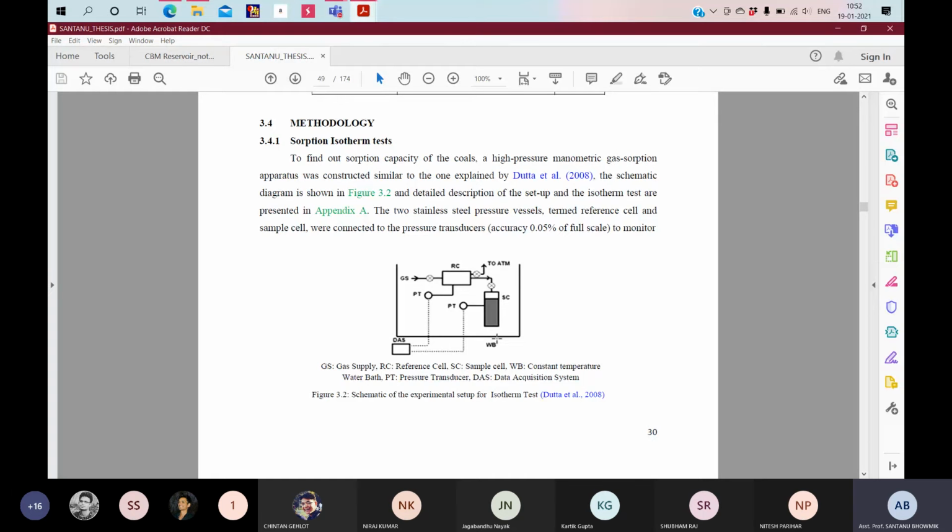The gas compressibility for liquid and solid is much less, but for gas, the compressibility is so high, it will increase exponentially. And I'll show you later that even if there is a variation in the Z factor, the compressibility factor, in the sixth decimal point, after the decimal point, then also there's a change in the graph.